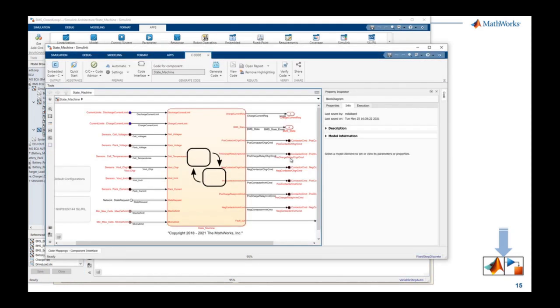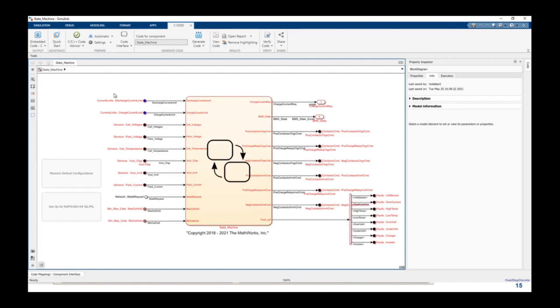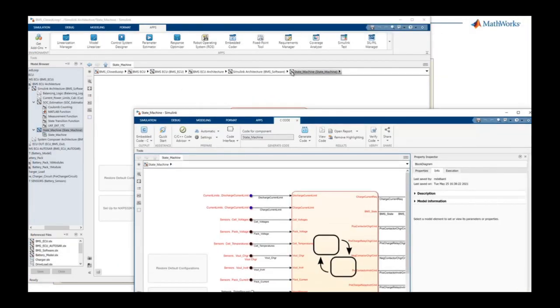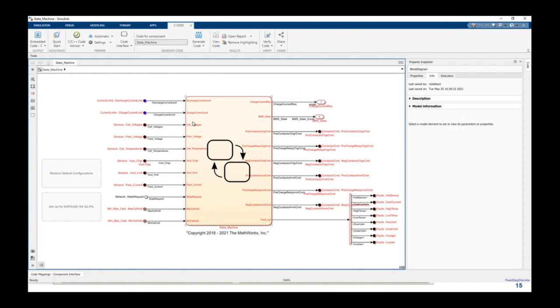Okay, let me open the embedded coder. Now I have opened the model as a separate model, because I don't know if you paid attention, but these are reference models. So when there is a reference model within your system, that means it's a completely separate Simulink model. That's why I have opened this subsystem as another Simulink file, and from there I can indeed generate code.